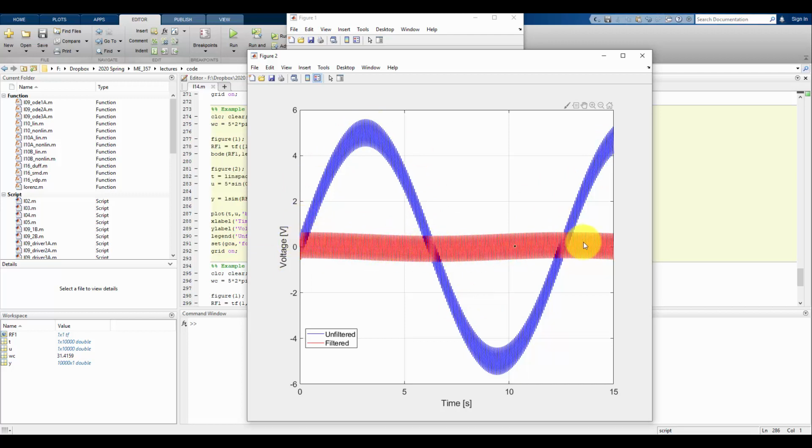We do see a little bit of that slow response happening, but again, we expect it to be only 1, maybe 2% of the amplitude it was originally based on the Bode diagram. Whereas that rapid 100 radian per second response is still visible there, and the amplitude is barely affected. Again, from the Bode diagram, it should be about 96% of what it was originally.